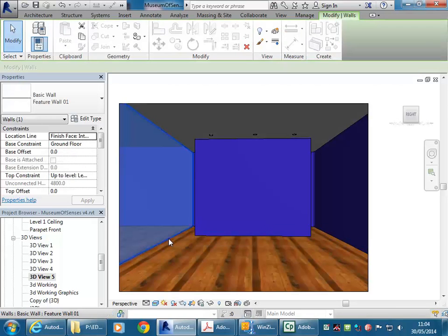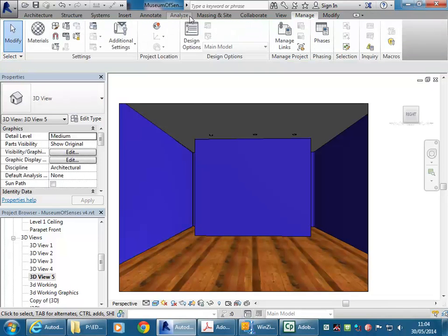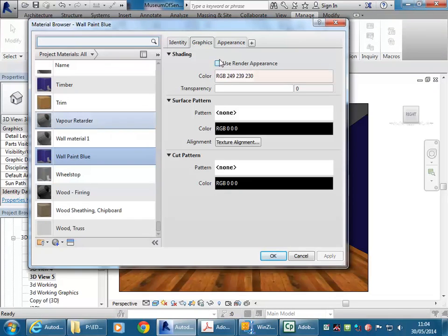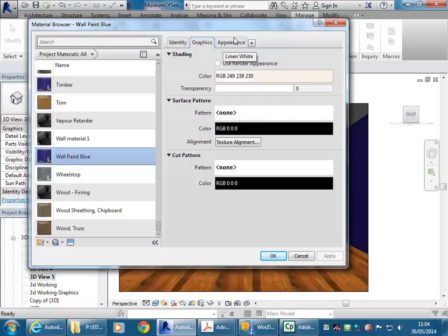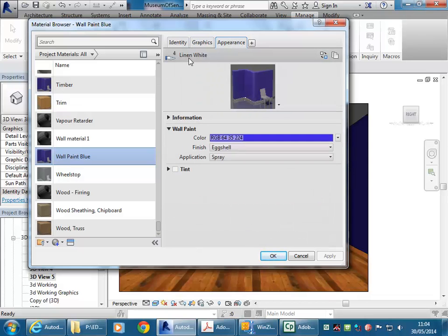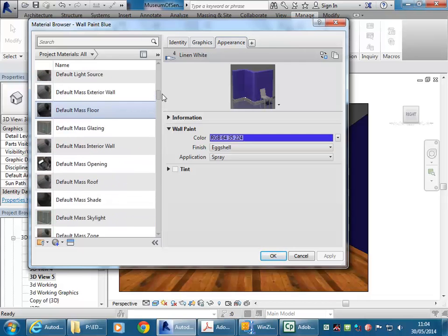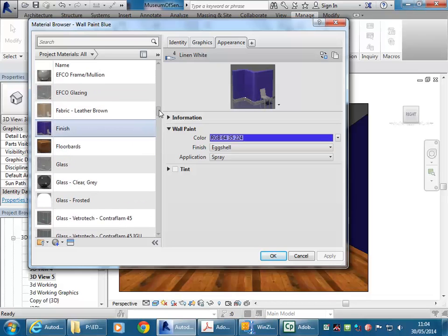Now I've gone and changed, what have I done there? Did I set my finish without duplicating, did I? Oh yes, I did. Okay, so I did something that you shouldn't do, but it's good to see this. I changed the original linen material because while I was talking, I forgot to duplicate. I forgot to replace. So going back to finish, here you can see it's using the same render material. And if you've been wondering why every time I go to replace, that is the reason.